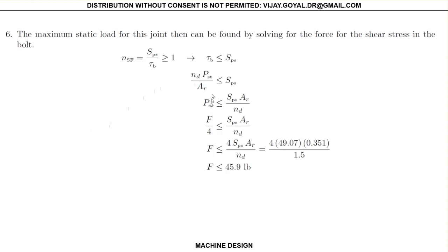And then from here, I solve for PST. I know this is 4, multiply 4 on both sides. And you can see that this is the maximum capability that my joint has. Okay, some recommendations that you could do is you could thicken your plate, you can change its plate material, you can choose a higher strength bolt, but you're going to pay a big price, so maybe it's more heavy as well, and maybe a combination, or recheck the whole configuration itself. So this concludes example number 4.